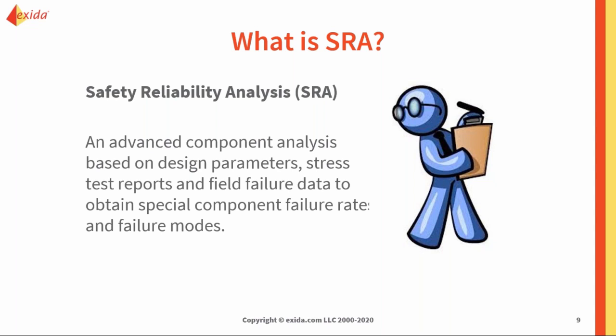However, if it's something that you want to highlight and look into, we can do that deep dive on those certain components. If you want to showcase what you're doing, if you want to show that you have lower failure rates, if it means something to your company, especially to your customers, they can use those lower failure rates in their SIL verification calculations. That could then affect their SIL calcs, which is a big deal to them.